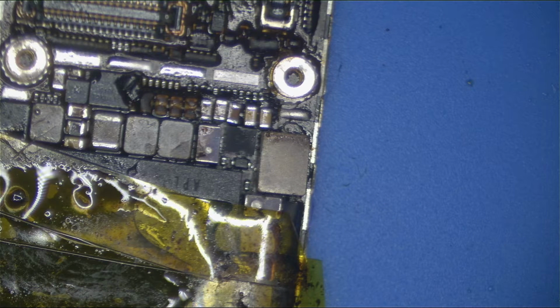I remember I was trying to figure out why all my iPhone 6 backlights were dim afterwards. I was checking all the filters, checking for partial shorts. I really had no idea what was going on. I was trying 6 different backlight ICs of all different revisions off of the older iPhones and the newer iPhones. No one ever suggests it's the coil, because it's never the coil.